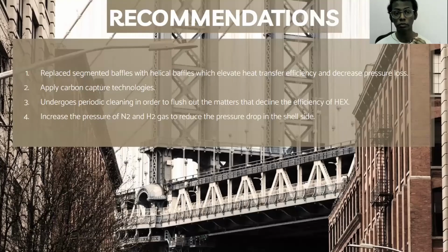And for the recommendations part, we need to replace the segmented baffles with helical baffles, which elevate heat transfer efficiency and decrease the pressure drop. We can apply carbon capture technologies. Another recommendation is we can undergo periodic cleaning in order to flush out the matters that decline the efficiency of the heat exchanger. And also we can increase the pressure of nitrogen and hydrogen gas to reduce the pressure drop in the shell side. So that's all from our group. Thank you.